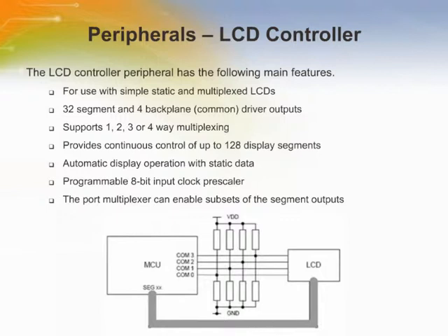The LCD controller provides the eCOG1X with hardware support for driving simple static or multiplexed LCDs. The diagram shows an example connection to the microcontroller for this LCD driving scheme. The common backplane outputs must have tri-state capability, and the external resistors provide the third voltage level at half the power supply voltage. The segment driver outputs are standard logic outputs.